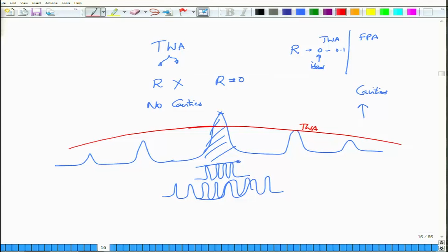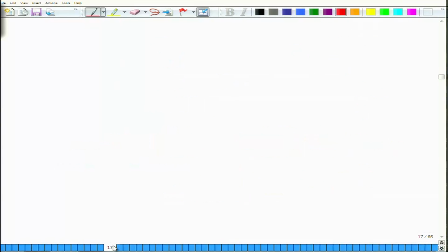So, you have to of course improve the single pass gain, because that is exactly equal to the gain of a travelling wave amplifier, by increasing gamma, increasing G, reducing alpha and increasing L. So, this has to be increasing, this has to be increasing, loss has to be reducing, and L has to be increasing, all with certain constraints and approximations. Even the bandwidth of a travelling wave amplifier will be much wider compared to that of the Fabry-Perot cavity. So, this is the travelling wave amplifier, and this is the overall gain that we talk about.